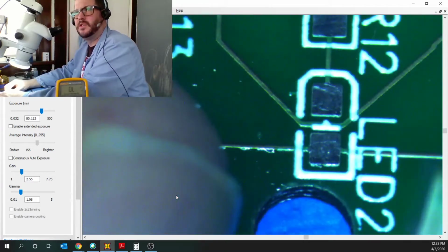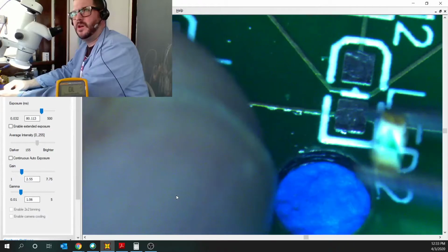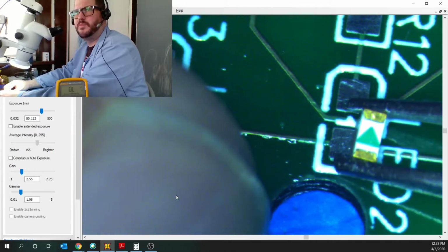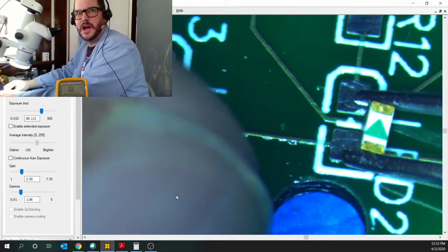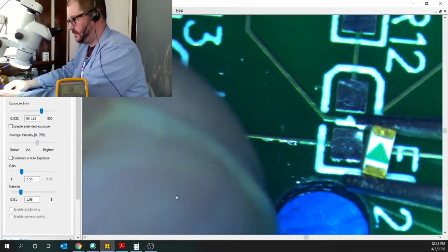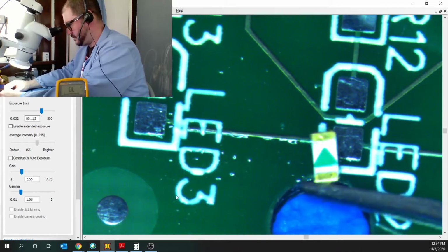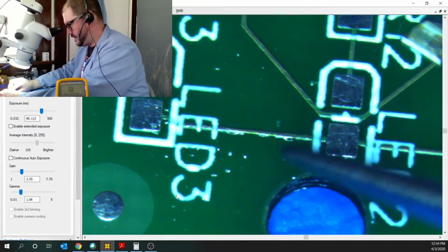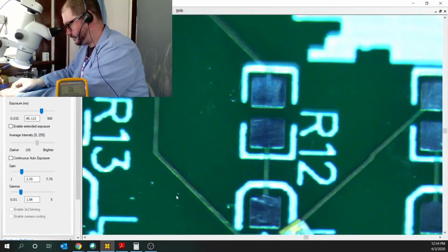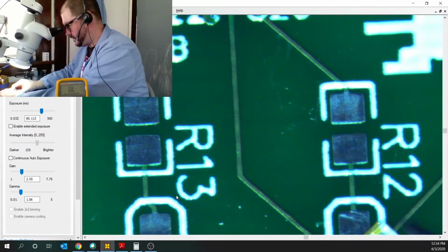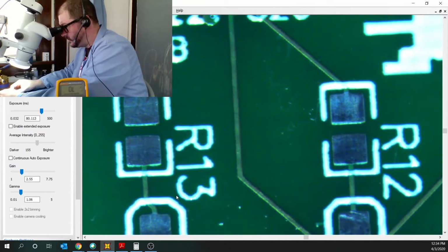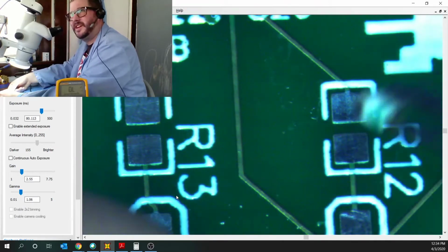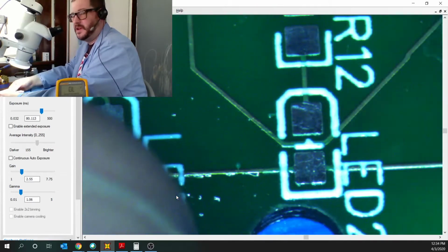So yeah, going back down to LED 2, I'm going to want to attach it so that the bottom part of the triangle is actually pointing up towards the marked part of the cathode there. So let me flip this guy over, and we will see that this is sort of a difficult thing to really be able to do. So we'll flip it over and we'll see. Oof! Can you see that there? The triangle is going to be on this side.